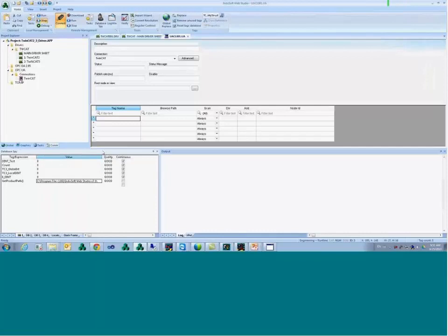So if I go to the Web Studio solution, you're going to go under Redist, and then WinCE 5.0, and I'm going to have all the platforms, whatever platform you have. Under the bin folder, you're going to find the cserver.exe. That's the one that you're looking for. Copy this file to your Beckhoff device, run it, and follow the procedure that I just did. You're going to install everything, both the runtime and anything else you need there. Okay?